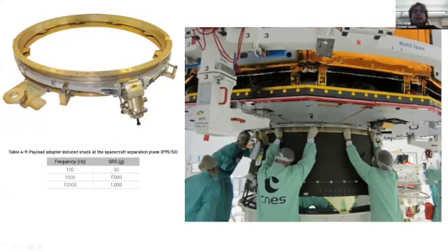And again, you can see that it's a shock spectrum, not a single frequency. It's a magnitude in G's defined at each frequency. And this really defines a curve, but they're showing you some discrete points in the curve. But it defines a magnitude of shock across a range of frequencies that are constituent in the shock excitation imparted on your payload at the high shock events.